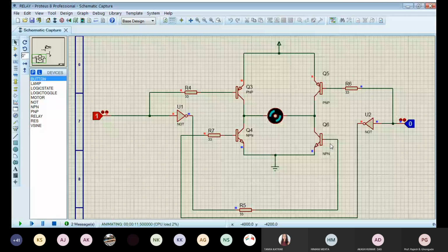So this is a very, very interesting circuit where you can control the direction of the motor. In most of the hobby projects, or let us say motorized projects, you require to have a control of the direction of the motor, forward, reverse, etc. So in that case, this bridge is normally used. Of course, nowadays people normally don't use such a kind of bridge, because integrated circuits which do have this bridge, which is fabricated on the chip itself. So many of the chips are available, but the basic mechanism remains the same.